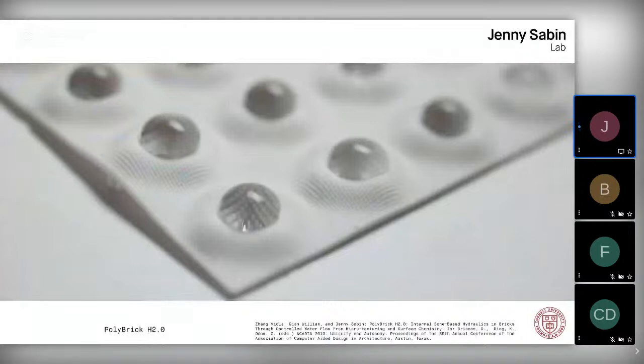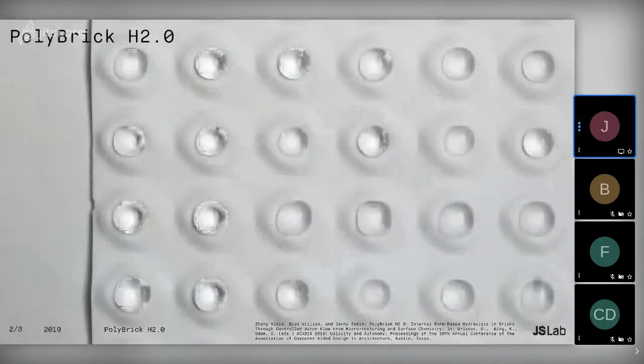And then lastly, and this is very recent work, we've begun to really push the microtexturing with these 3D printed ceramic tiles. This particular example informed by the texturing of pitcher plants which are super hydrophobic. So by steering the actual texturing, as you can see here with these dimples, we can control the flow of water. And so here, the same tile is shown at a vertical orientation where you can see those droplets of water are not moving, but staying within those dimples.